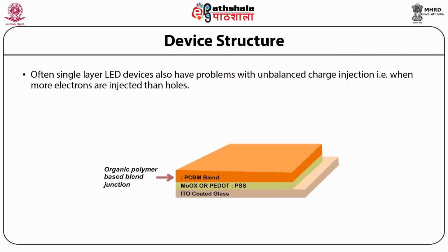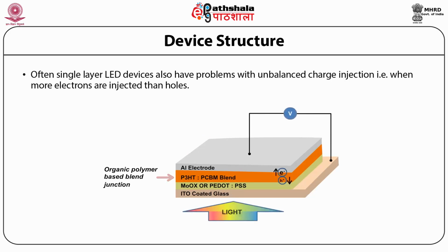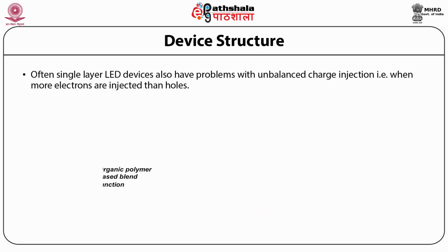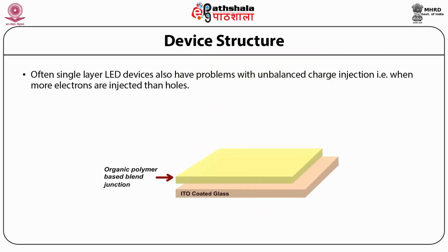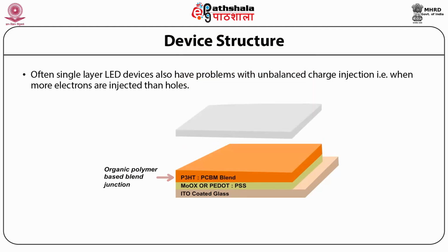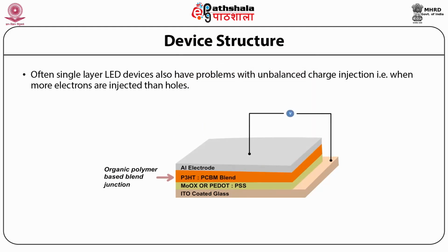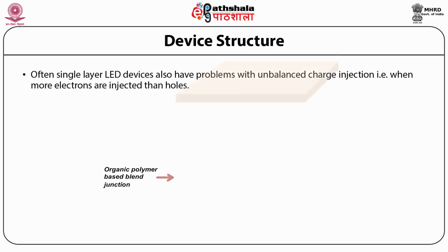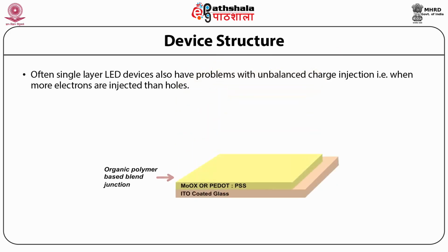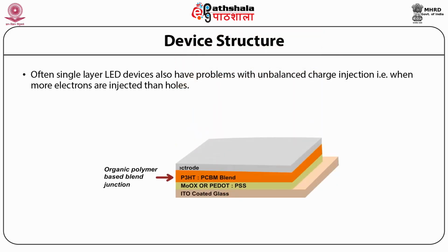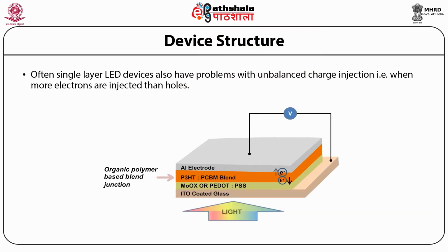They are implemented so that one can use a thicker layer of materials, say up to about 100 nanometers, so as to be able to absorb more light whilst not losing on the number of dissociated charge carriers. A typical organic solar cell consisting of an active layer sandwiched between the cathode and the anode is shown in this figure.